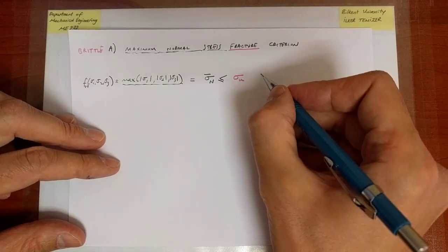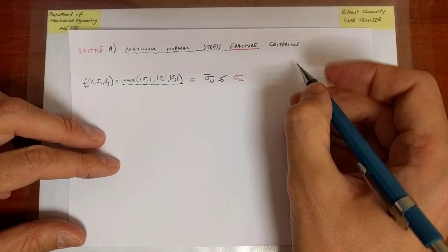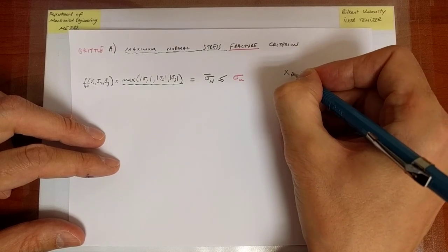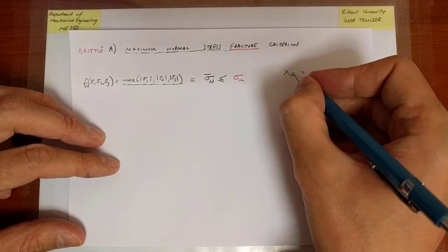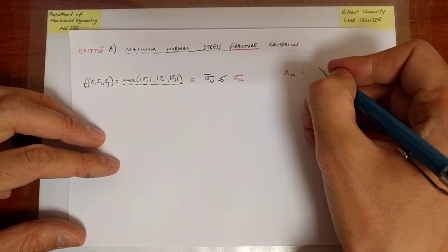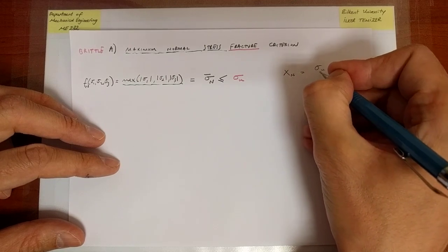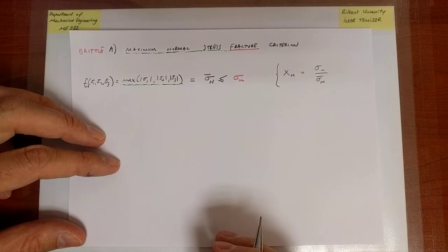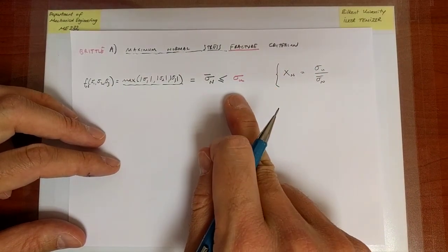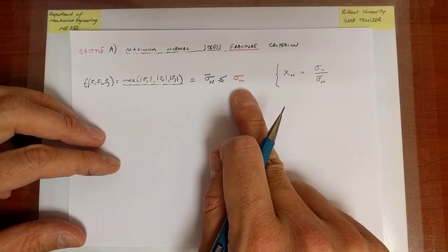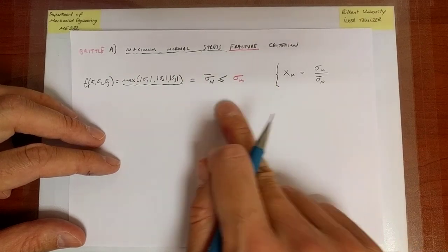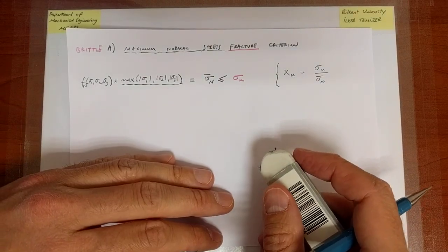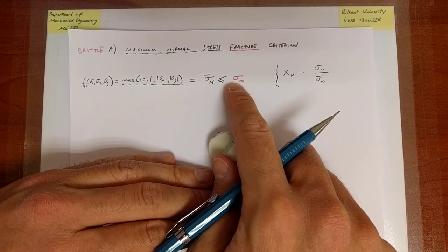Now, subsequently, I can of course calculate the safety factor for this criterion. Again, N indicates that we have a normal stress criterion, and the safety factor is sigma u over sigma bar N. Now, having said that, I will do something that will always remind us how to eventually determine what the critical limit to this structure, to this material behavior is.